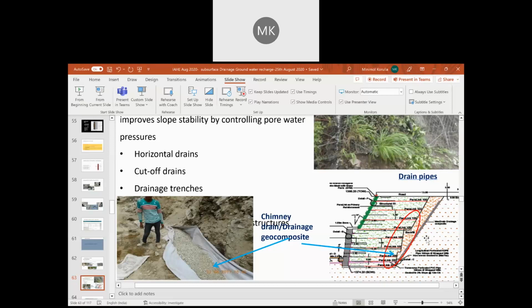Okay, so even if it is showing an excavation with some good dimensions, in fact the width is quite small and the depth is significant, and the filter fabric can be introduced there, which will act as a subsurface drain effectively and which will carry to a longer length. Okay, and once it is closed, the space consumption is absolutely nothing. So the entire subsurface flow will be taken care of by this.